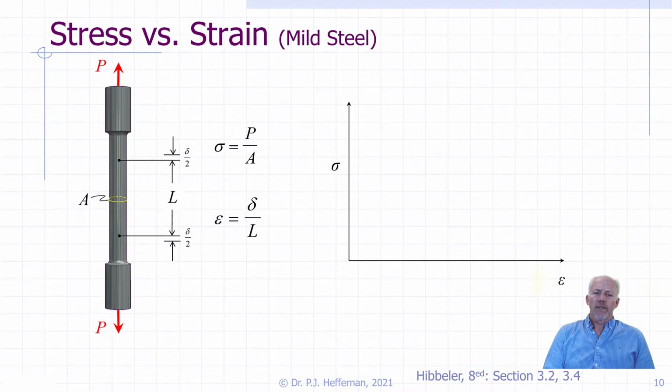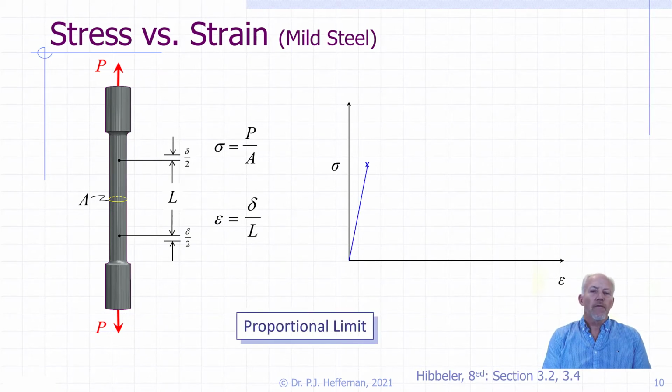The stress strain diagram is a fundamental description of the material capacity when loaded uniaxially. For this ductile material, a classic stress strain curve will have several distinct points and regions. The following properties are obtained from the stress strain diagram and are shown as we build it through incrementing loads. The first point of significance we get at the end of this linear elastic portion is the proportional limit. Beyond the proportional limit, stress is no longer proportional to strain, i.e. the linear portion of the curve is no longer followed.